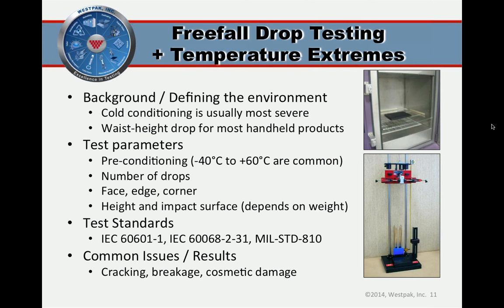However, with most plastic parts, plastic housings, and also glass actually as well, things become more brittle with colder temperature, and also things become very soft with highly elevated temperature. So with all these things, you need to start by defining your environment and considering what extreme environments your product may be exposed to. In general, cold is more severe than warm for this type of testing, but not always.